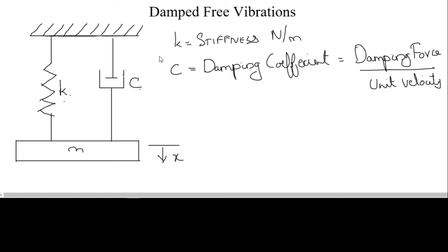So we know damping is given to absorb the vibration. So a free hanging system or a spring mass system, compared to this one, will have more vibration because here there is this damping, and damping can be associated with shock absorbers of vehicles or springs in vehicles. All of those carry the same function as damping, that is to absorb vibration and reduce vibration or stress in the material. So to derive the equation of motion, let's consider the free body diagram of this mass.